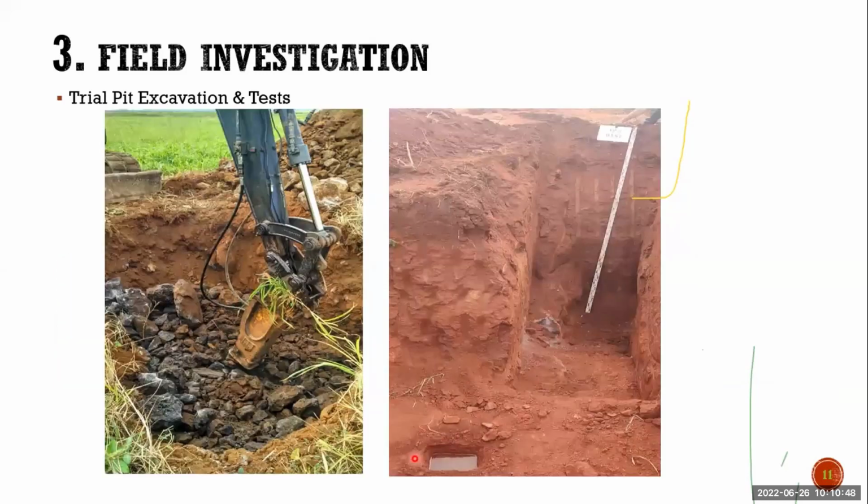And see here, this one you can see very clearly. So we are getting the stiff clay silt soil here after the topsoil, and that clay silt soil is extending up to, see, there's a staff here. Normally to measure the depth, we'll keep the staff, and we'll take the picture, and you can see. And if there is any percolation test required, then they will do this test. Mainly they will do this test to design the sewage. If any sewage disposal needs to be done in that particular location of the site, they'll perform this test.